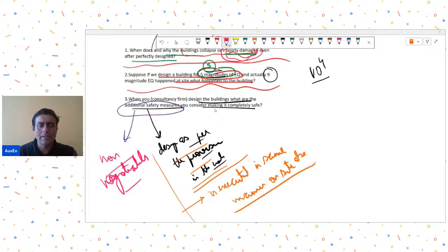Or to give you another example, let's say beam stirrups are quite important, or the development length in your bars, especially the top bars in beams, is quite important. So that may be one of your non-negotiables. Non-negotiable means where, as an engineer, you should ensure that whatever you had designed is getting executed as it is on site, and there cannot be any compromises in that.